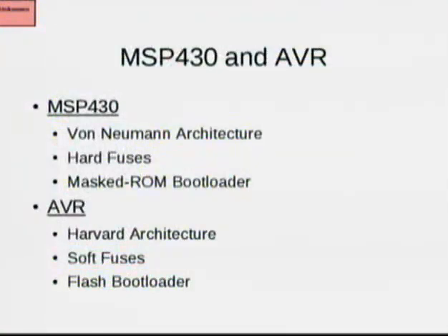And in certain versions of the bootloader, I found a timing attack, which you might remember me presenting at the Congress in December, which allows you to guess the password 1 byte at a time. For every guess of the password you make on these vulnerable chips, the password comparison takes 2 clock cycles longer. So you can run your password, measure the amount of time, and then if you send your traffic in the correct weird way, the difference between your beginning the broadcast and getting back a non-acknowledgement telling you that your password is wrong reveals the password.